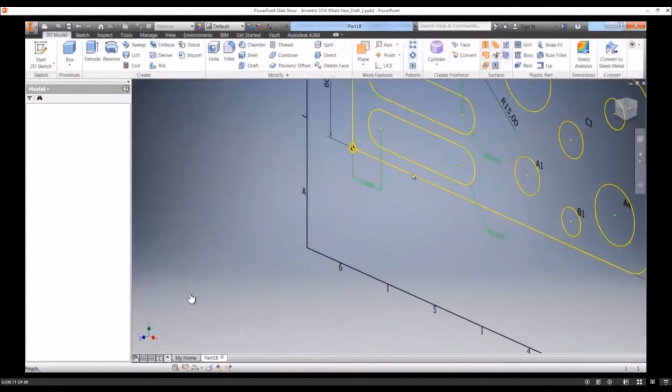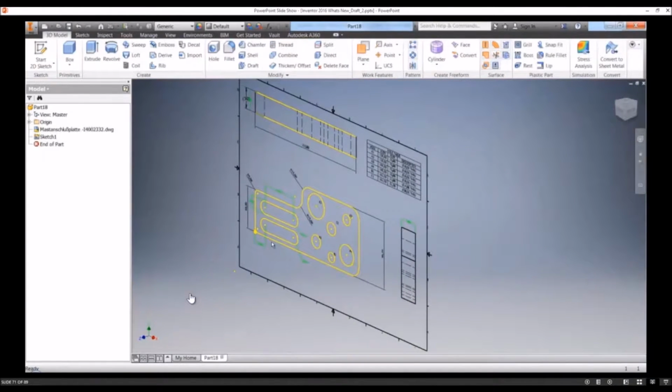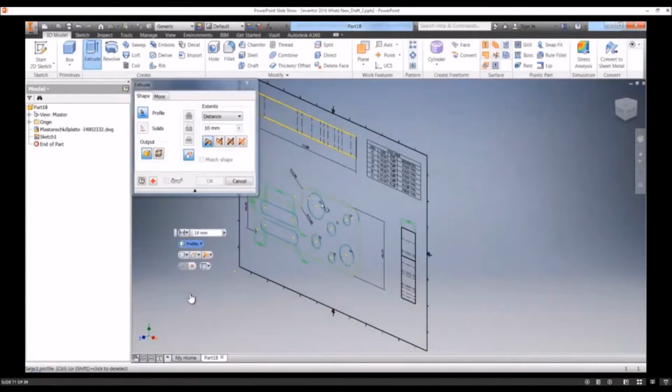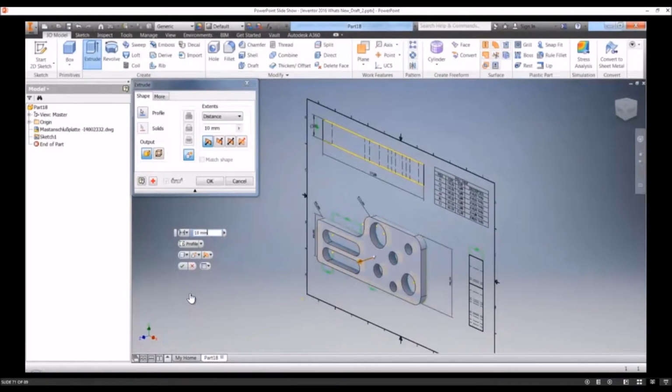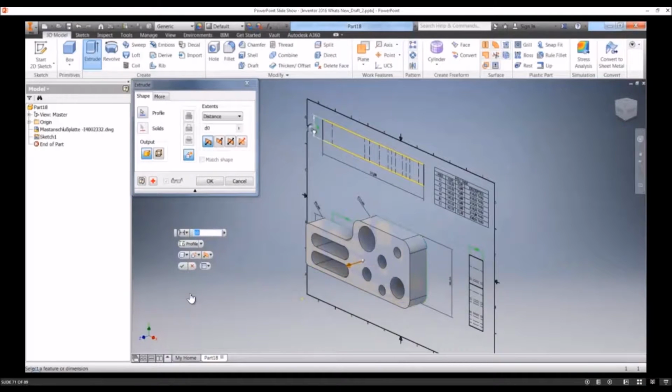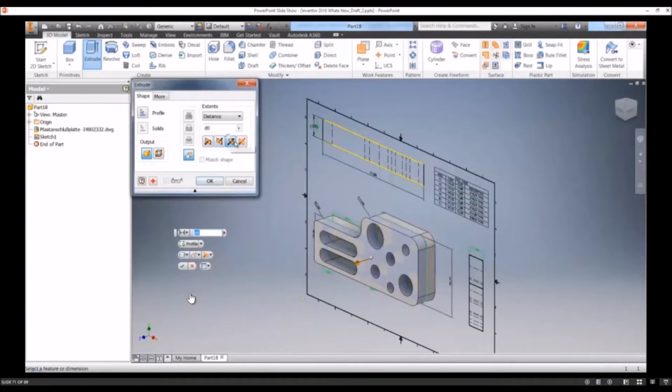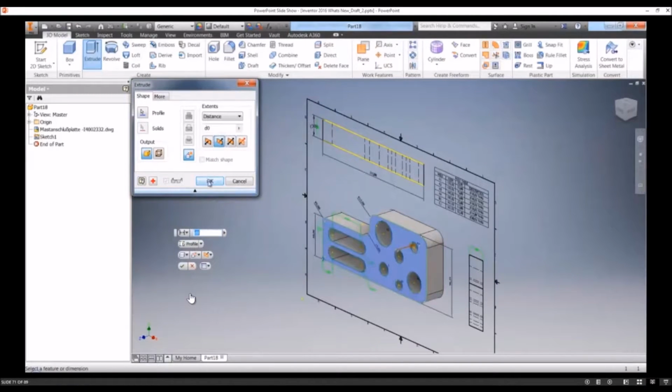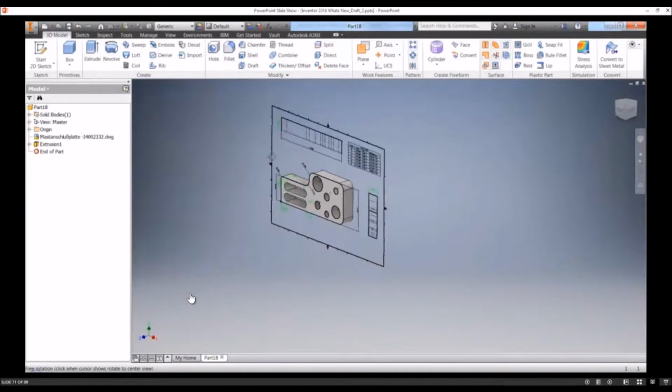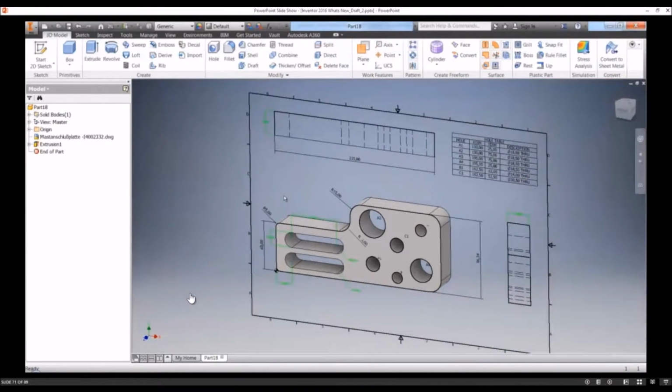And then when I've finished I can simply finish the sketch and really quickly create an extrusion of my profile that I've just copied out of AutoCAD. So my dimension value, this is where you can start being intelligent. If I link my dimension value to the reference dimension I've created, in effect I've now got a fully controlled Inventor file that's controlled by AutoCAD.